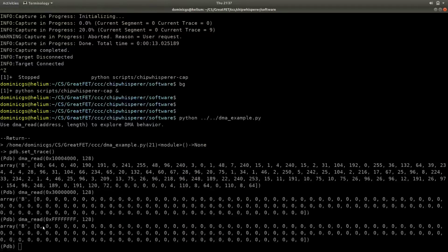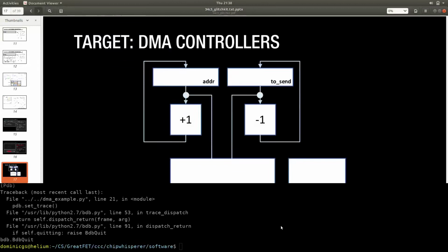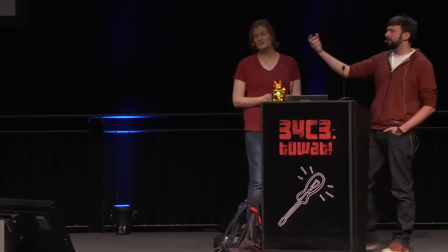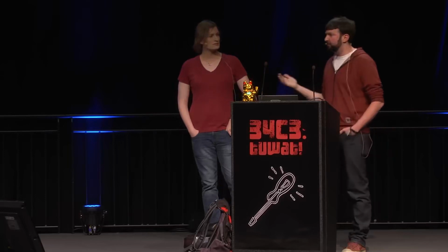Yeah. So this gives us almost unlimited opportunity, if we're willing to read absurd amounts of data, to explore the address space. And if we happen to, for example, corrupt a length field that's supposed to have a value of 10 and is 32 bits long, and we get something that's really, really long, there's chances that we're going to get things that are, after that in memory, wrapping back around and starting again. Yeah, exactly. So if we do manage to take the 32-bit length field and glitch it to become -1, jump that comparison to 0, and get it to become -1, it will continue reading all the way around until that integer loops, which happens to be about the point that memory loops on this thing. So we get all of RAM.